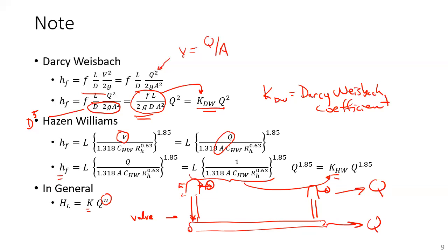And very often we'll do this at night when we know there's not a lot of flow in the pipes, that people aren't using a lot of water. So this hydrant flow is dominating. And so in this case, if we take 0.1 at the first hydrant to the left and 0.2 on the right, what we would say is that the total energy at 1 is equal to the total energy at 2 plus all of the energy losses.